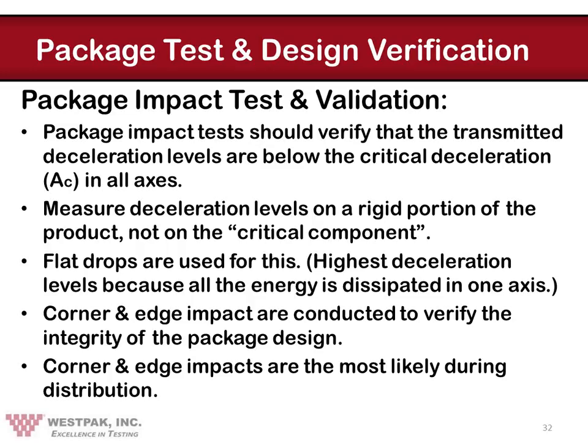Let's talk a little bit about shock, or impact. These impact tests should verify that the deceleration levels are below what we need, and we measure that by putting an accelerometer, typically, on a rigid portion of the product. Now, a rigid portion of the product, that's not the critical component, because we already know what that does. So what we want to find out is the input to the package system. We're not measuring the package response.